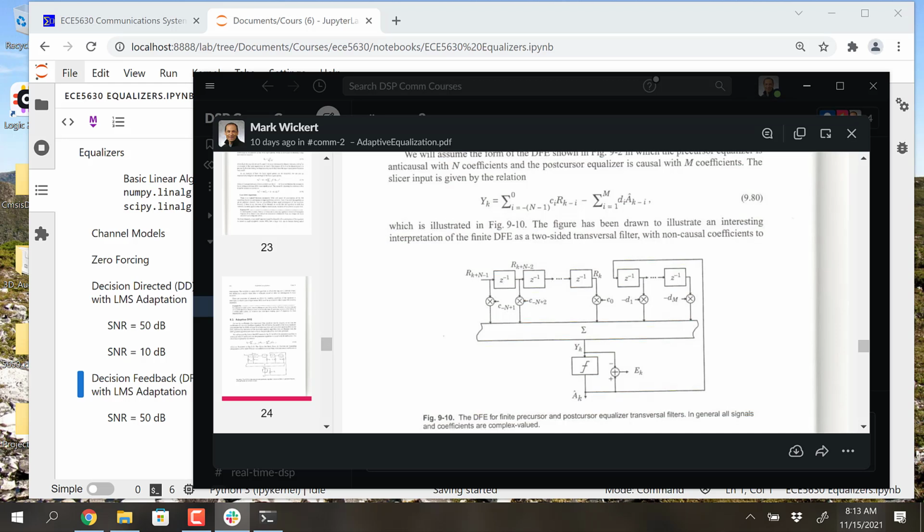But the feedback values are the hard decision values that come around and wrap around so that the very first input, which comes out of here instantaneously when we're making our samples over here, comes around and then gets delayed by one sample, so that it's not the present sample. This is the coefficient that goes with the present sample. This one is one sample later on the timeline, which is why there's the z to the minus 1. Even though this operation of slicing happens essentially instantaneously, when you command it, it'll do it. But it has to be taken one sample late.